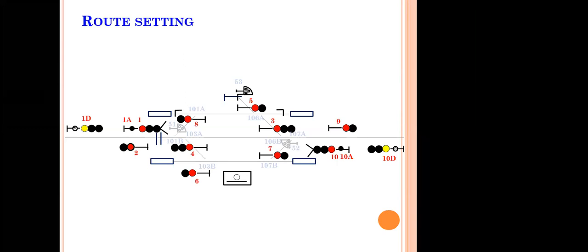Second question comes: a trolley. Somebody has put a trolley. Correct. There are two types of trolleys. One is called an insulated push trolley. As the name indicates, it is insulated. It can be lifted immediately from the track the moment the guys see it, by two people. The wheels are insulated, the axle is insulated, so the two rails will not get shorted.